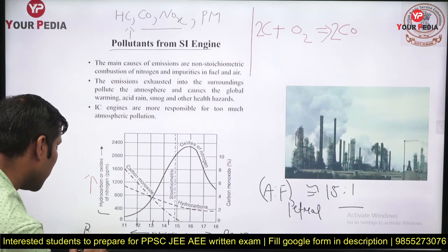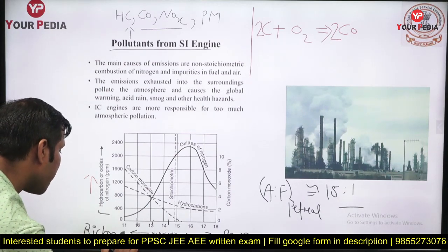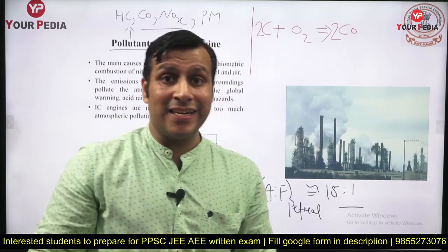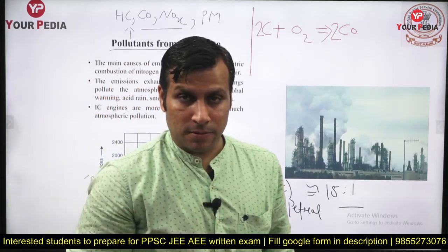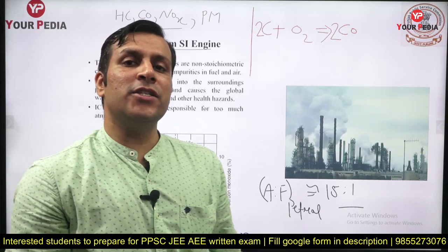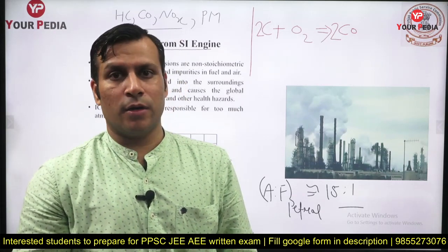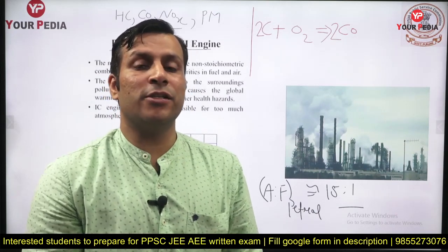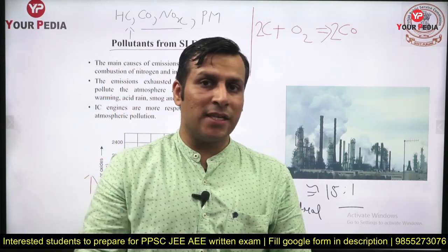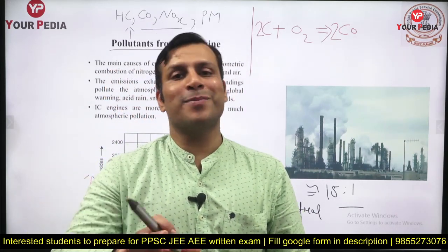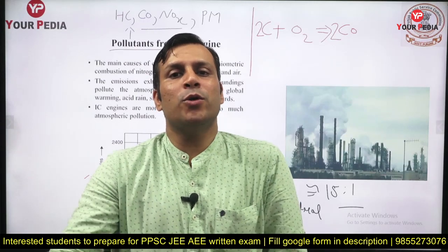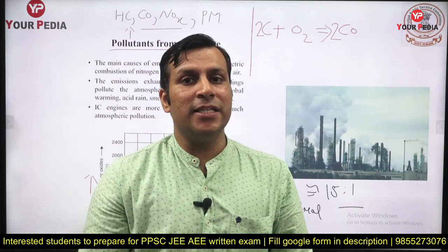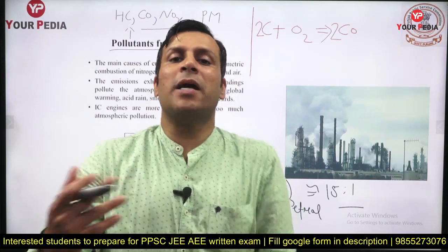Here richness, more fuel. If more fuel is there, obviously that is required sometimes due to idling condition, due to cold starting condition. When you are initially starting the engine, that is known as cold starting, because the engine temperature is very low. In that case, if you supply the stoichiometric air fuel ratio, you will not be able to carry out the combustion. So initially, for starting an engine under cold starting condition, we need to supply a rich mixture.